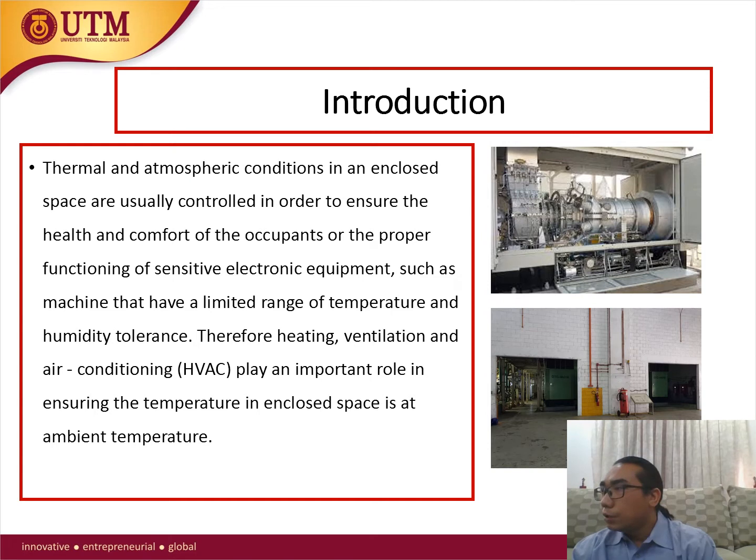What constitutes extreme conditions can be interpreted in many ways. Generally, for an office, it would be assumed to be a clear sunlit day with high outdoor wet bulb and dry bulb temperatures, high office occupancy, and correspondingly high use of equipment and lights. Design conditions assumed for a cooling load determination are subjective. However, after the design conditions are agreed upon, the design cooling load represents the maximum or peak heat extraction rate under those conditions.